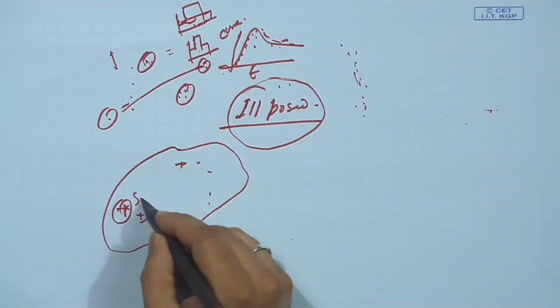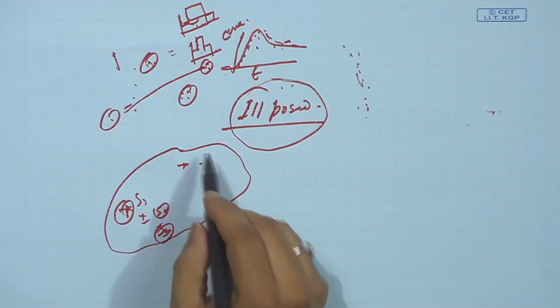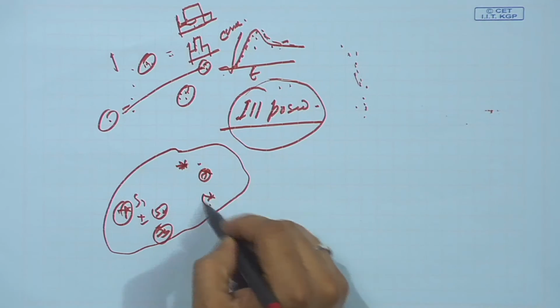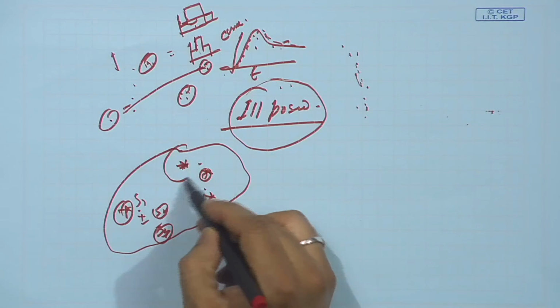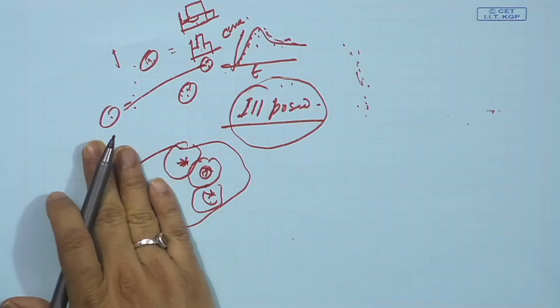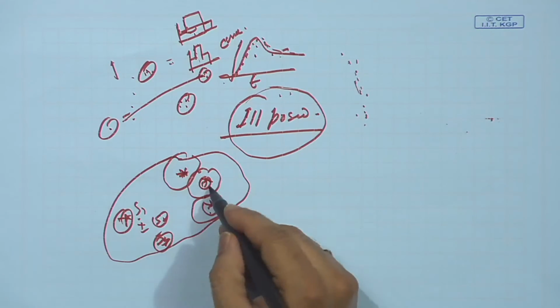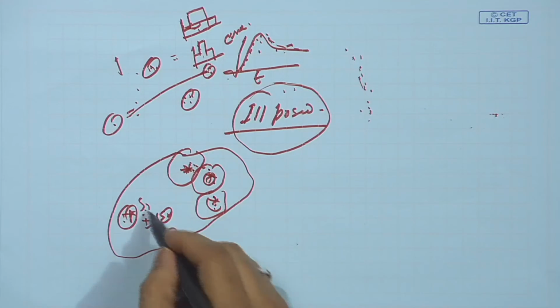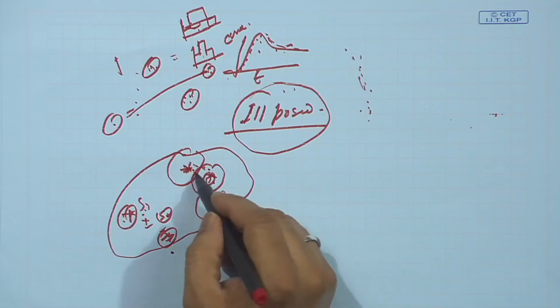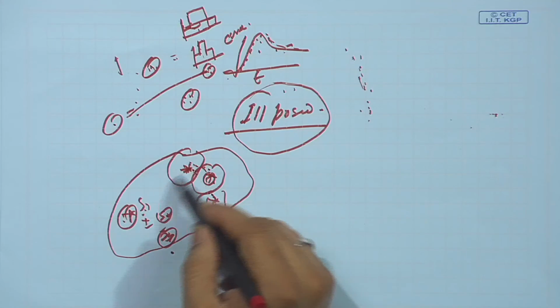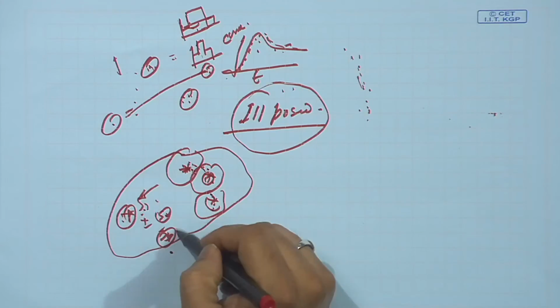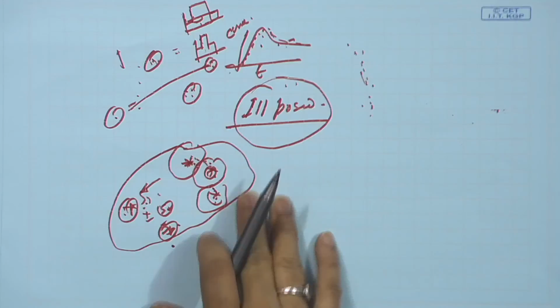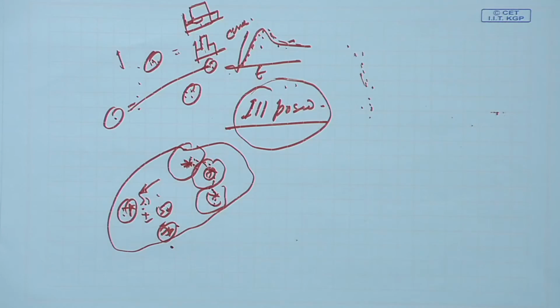But what we do is take a hypothetical area where we assume that I know the sources S1, S2 and S3, whatever they are, and then find out what the concentrations will be at these locations if these are the sources. Then use these as my measured values of concentrations and forget that I know the sources. Put these input values in the objective function as the observed concentrations, and then try to find out what S1, S2, S3 are. From that I am trying to estimate the sources S1, S2, S3, and because I know for which S1, S2, S3 I got this observation, I can then compare.